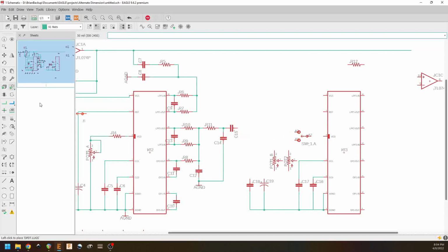And what this means is that our pin 6 can be connected either to his own independent potentiometer or to the second half of our dual gang potentiometer for time 1. These guys are going to get wired up exactly the same, just as a variable resistor.